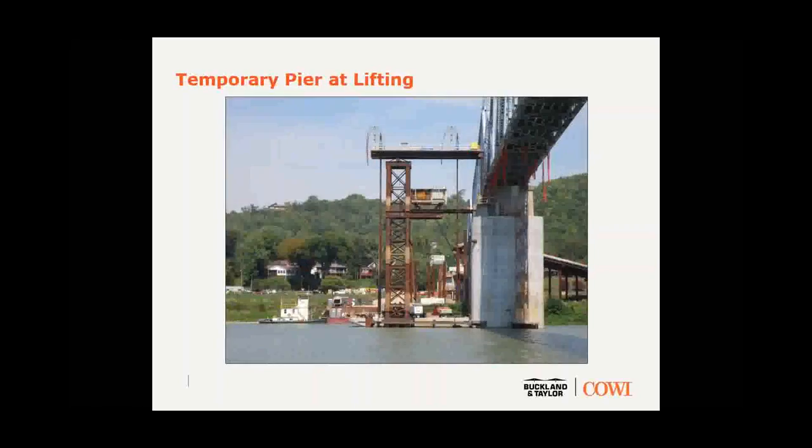So there's a complete temporary pier ready for lifting. You can see the strand jack, the blue jacks up on top of the lifting frame at the very top, and the strands coming down, and then the strand loops up and goes over a rollover. So as you lift, the other end of that strand just keeps going over the rollover and goes back down towards the river level. But if you look at the two vertical lines that represent the strand jacks, that's the two truss planes. We have one pair of jacks lifting at each truss.